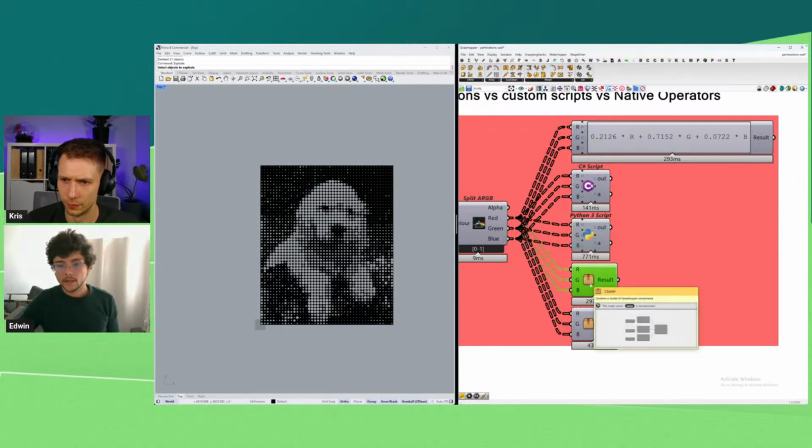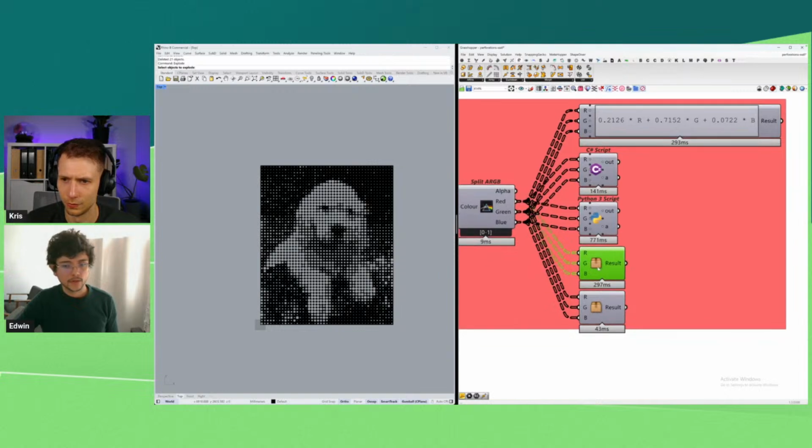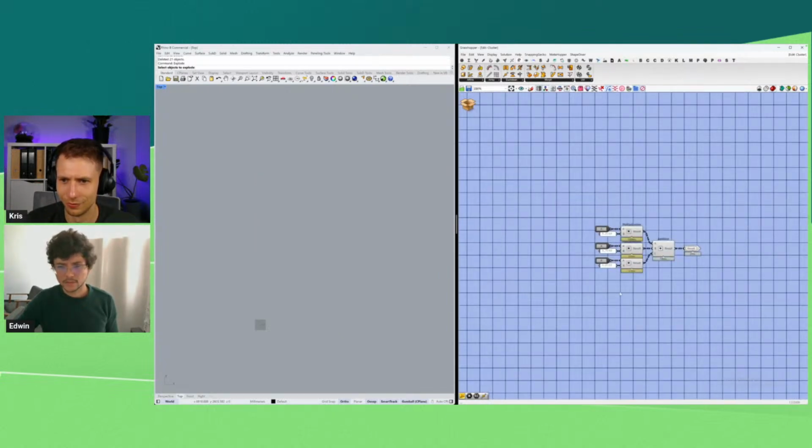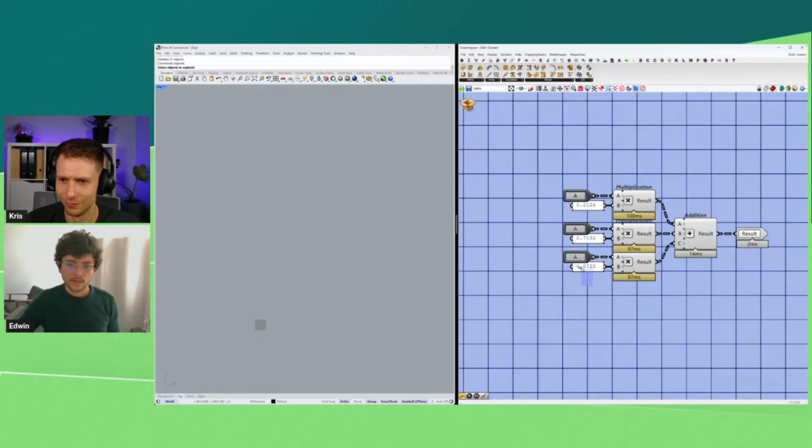And then we have a simple but very important error that many people make and have seen. For example, here I'm using a panel to do a multiplication. What happens here? Correct. The problem of using a panel is that a panel is actually text. Whenever you use a panel, it's text, it's a string. It's the same as if I do this. If I were to internalize this, it is the same as this.